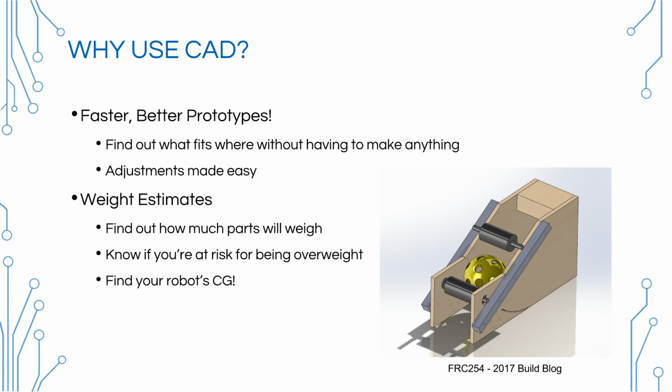It also helps if you're trying to do something that Apex calls high fidelity prototypes. Sometimes we don't have time to completely mock up a system that we just have an idea of. But what we'll do is, while we're designing the robot, we'll design the system as we think it should be, and then right before we commit to the design, we'll build it as quickly as we can out of wood or metal or whatever to the exact dimensions that we've designed the robot to, and make sure it works. And if it does, great. We validated that everything does what it's supposed to.